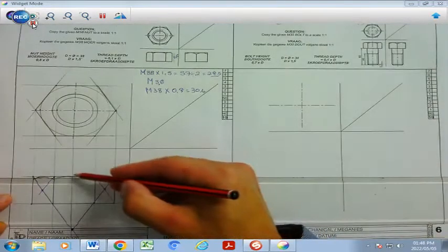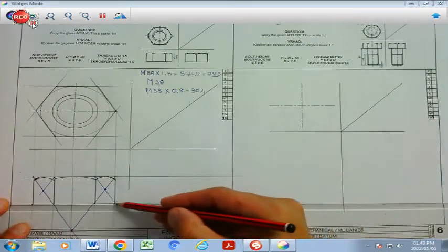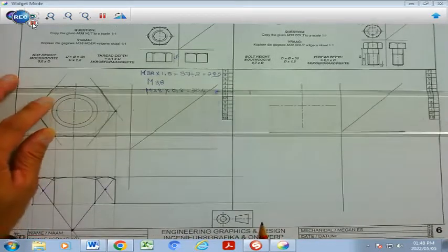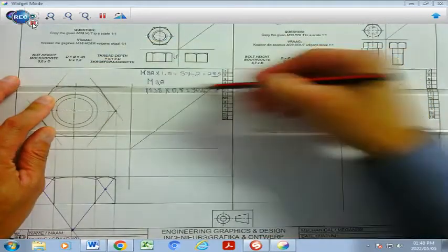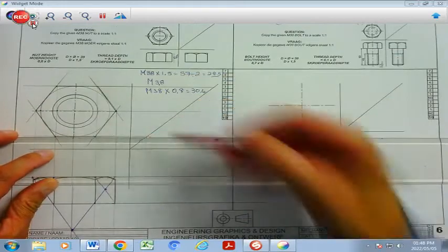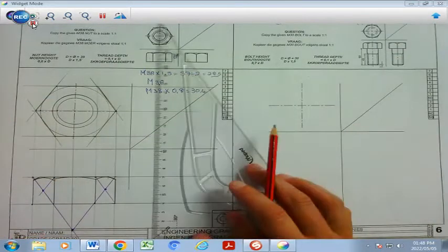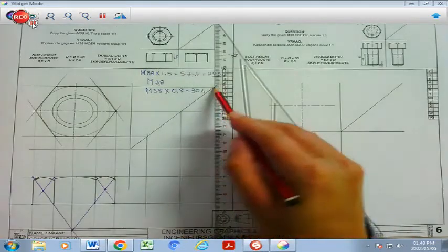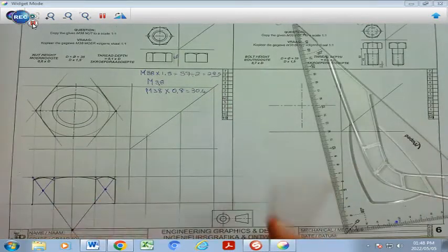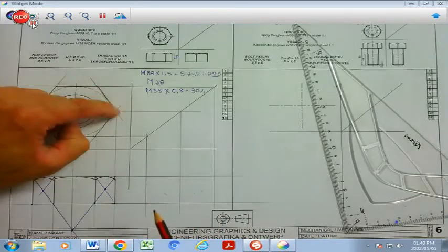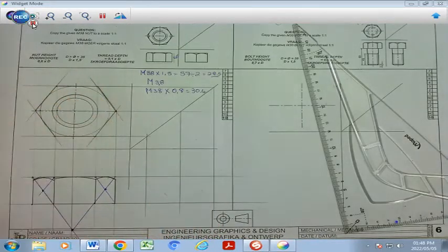I'm firstly going to project my height and my base of my front view across to my right view, as well as all the lines in my top view and my points onto my 45-degree line, like that there, and then I will project them down into the space here where my right view will formulate. Already you can see that I have created the 2 faces by doing that, this being face 1 and that face 2, coming from that slanted side and this slanted side here.